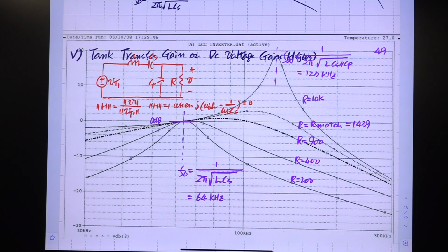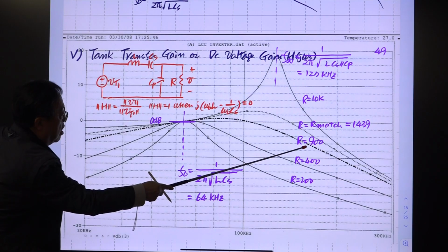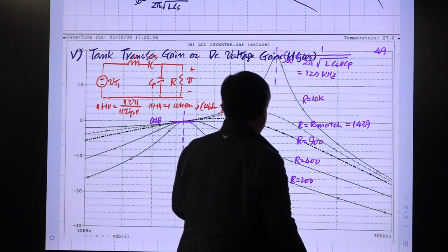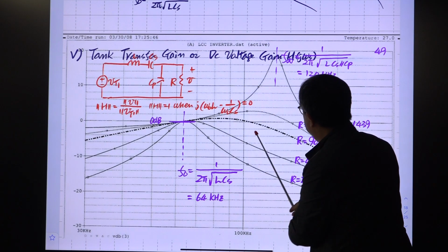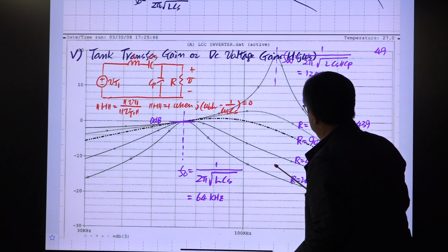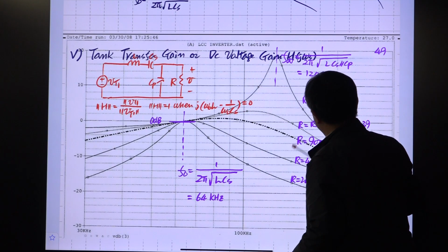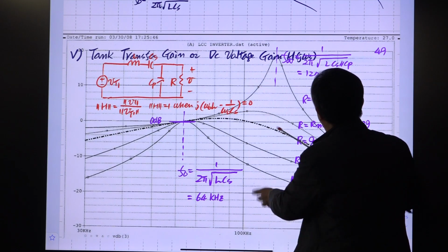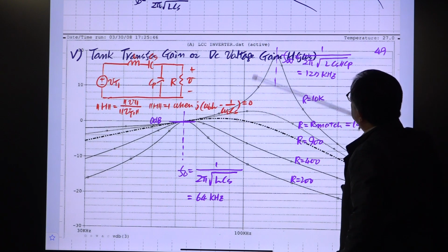This is the PSpice simulation, just simulation of this transfer function from here to there. Right? Then with relatively small R, 200, this curve, 400, 900, and the switching frequency of our converter was somewhere here. Somewhere here. Something is wrong. Okay. Then if you increase further for 10 kilo ohm, you have this. If you increase further, it goes like this.